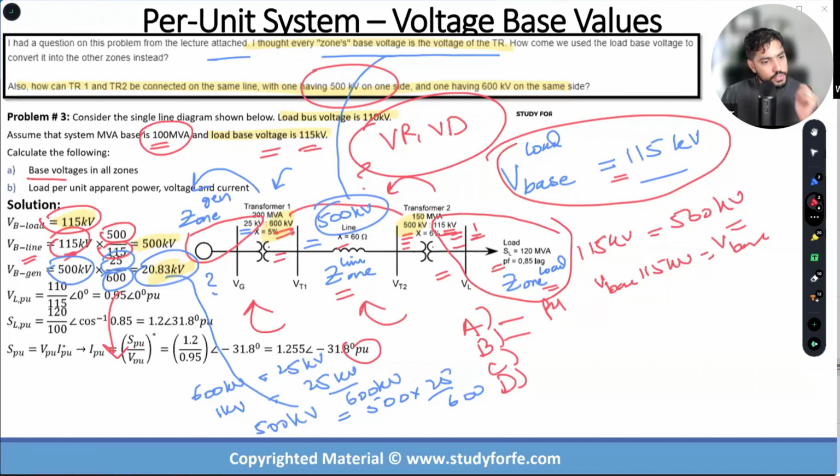All right, I'm going to take this question here. One question, maybe just me thinking about it too hard, but when we say primary of a transformer, is it always to the left? Yes. Okay, on the SLDs, that's a general convention. The top, if you're looking at it vertically, is the primary, and the bottom is the secondary. If you're looking at a SLD from left to right, just like how we have over here horizontally, then the left is the primary and the right is the secondary.